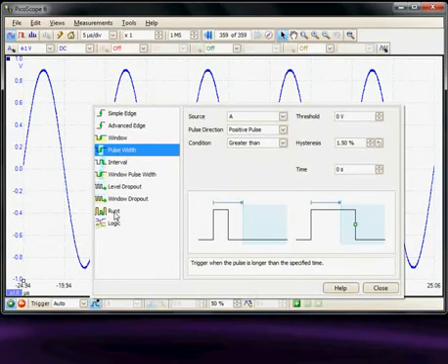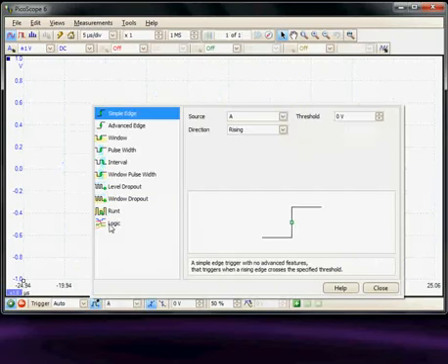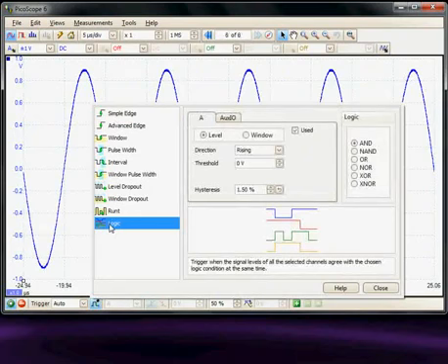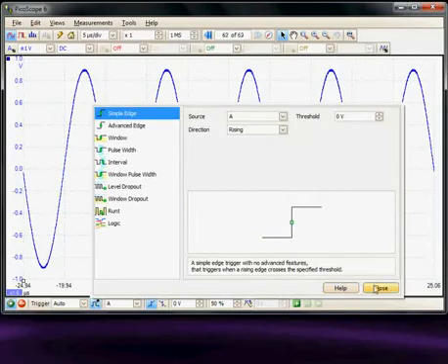In the advanced trigger library, we also have the run trigger. So this is an amplitude advanced library where we have two trigger levels, and we can trigger when a non-full height pulse occurs in a sequence. A logic trigger is also provided, so here we can use the 4 input channels and provide a logic trigger. I'll return the trigger to the simple edge trigger.